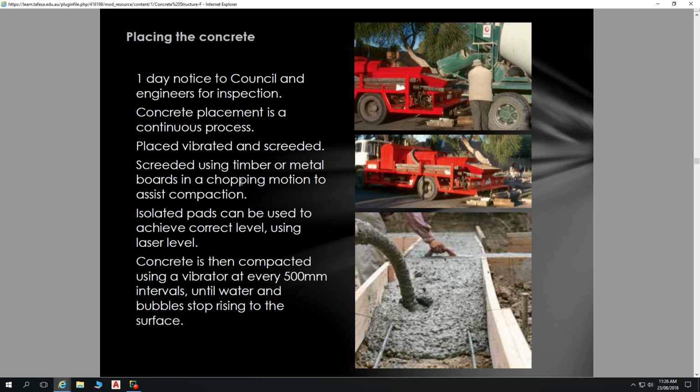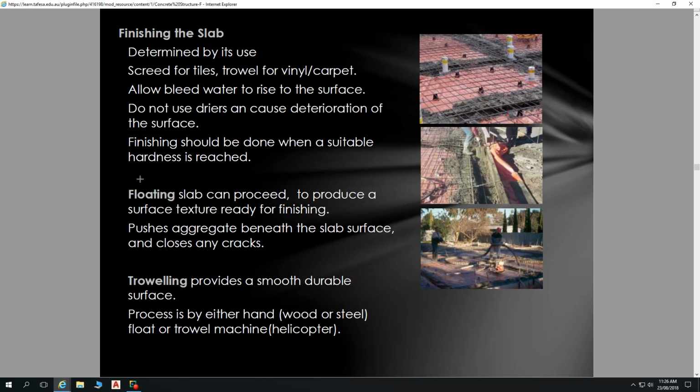So a bit of an apprentice job, but there's also skill to that as well. So then the concrete goes down. The process of concrete placement is about starting off working with large undulations to smaller undulations, to the point that we might do a really smooth steel trowel finish, like you see in a Bunnings warehouse or so.